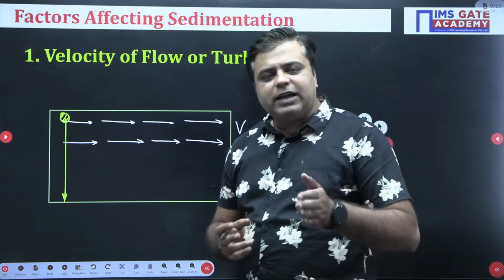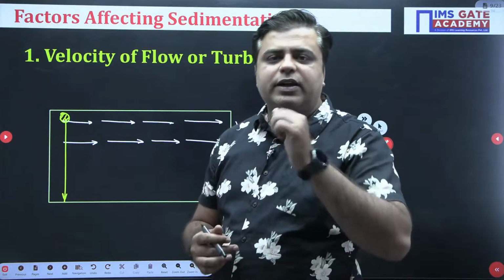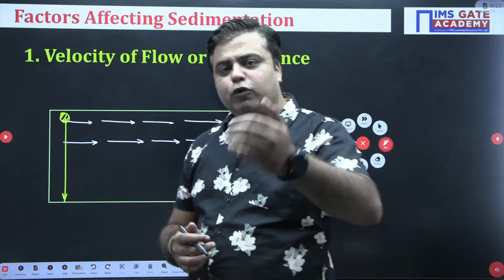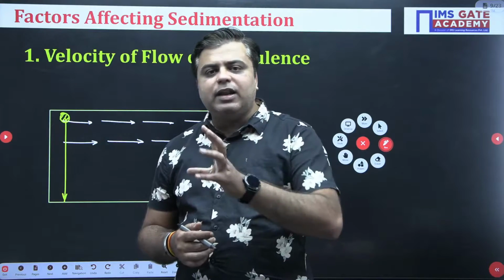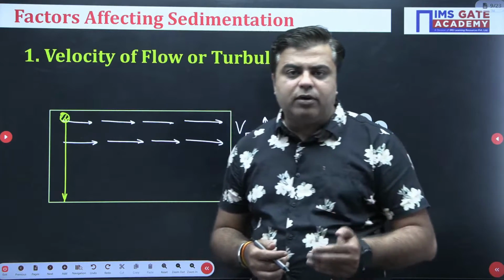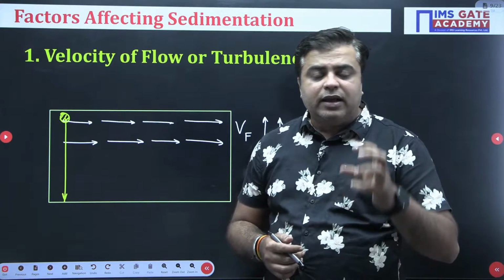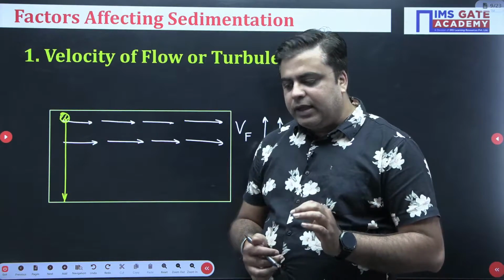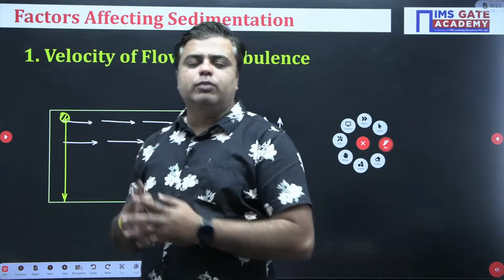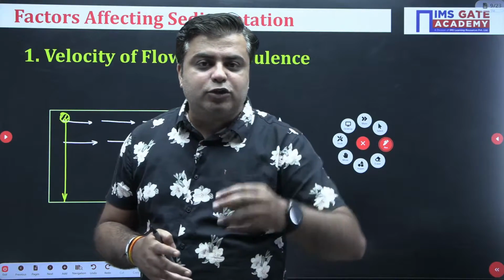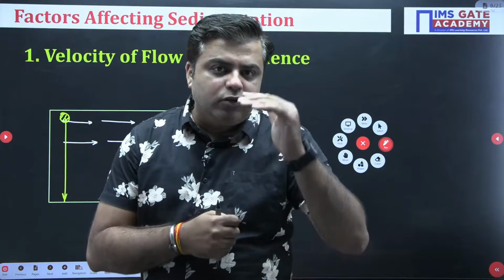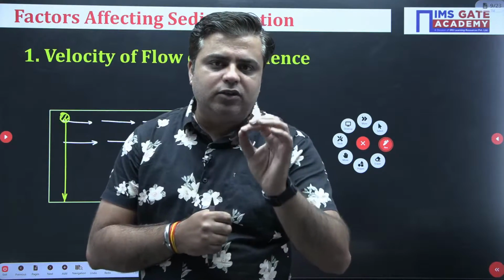And if the particle is not reaching the bottom of the tank, it is not removed. So if the velocity of flow is too much, the time available with the particle to reach the bottom of the tank is not there, hence the particle is not removed. In simple words, if the velocity of flow is too much, then the settling of the solids will be less, because the time available with the particle to reach the bottom of the tank is not present.